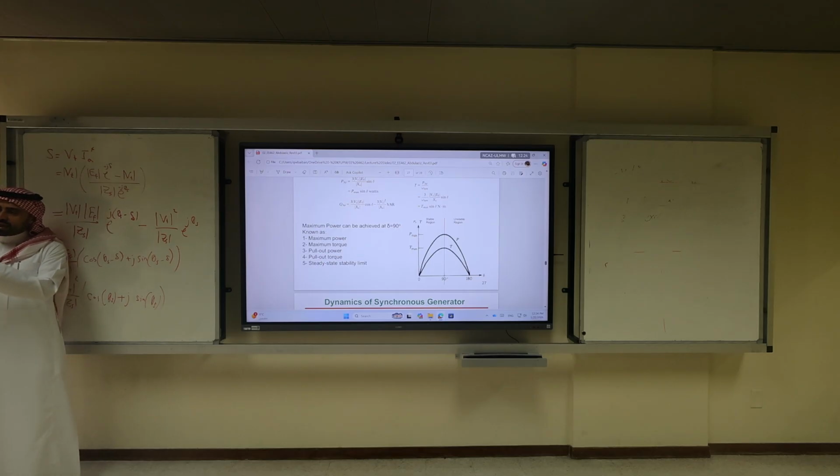If they are 90 degrees or more, the coupling between the magnetic fluxes is not stable. They would lose synchronism, and maybe that particular south pole would lose the coupling with that north pole, and it will try to find another pole that is closer in terms of electrical degrees.